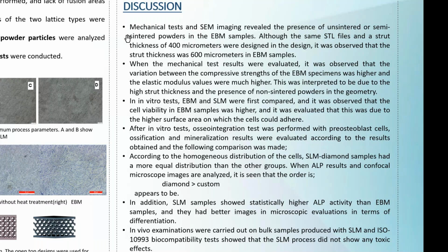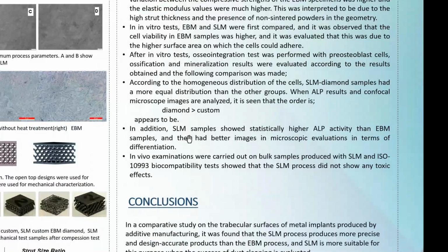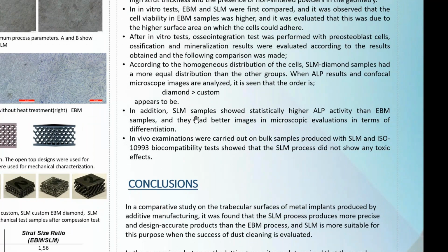After the in vitro tests, we conducted osseointegration tests with pre-osteoblast cells, and ossification and mineralization results were evaluated. With the mineralization results, we saw that EBM diamond samples had a more equal distribution than the other groups, and the diamond lattice unit cell was better than the custom unit cell.